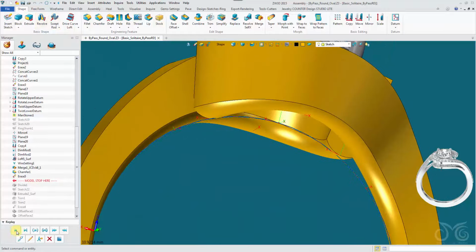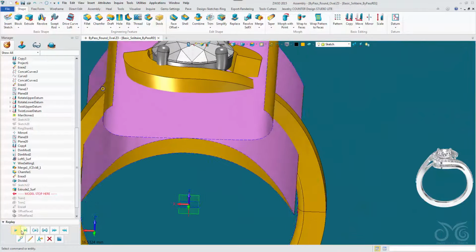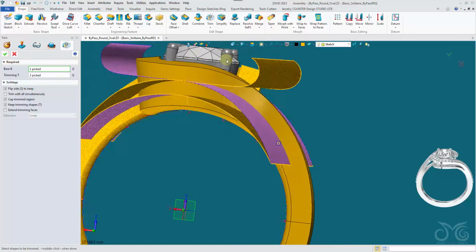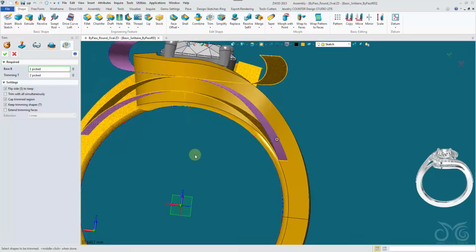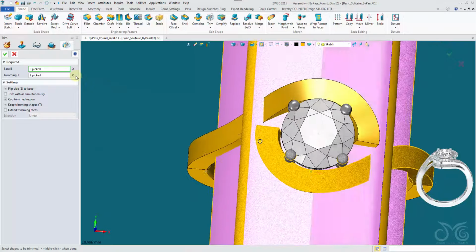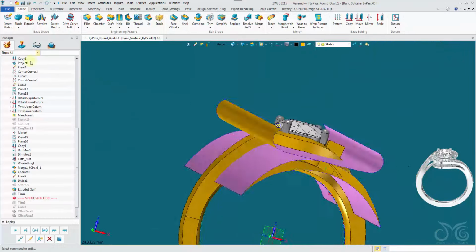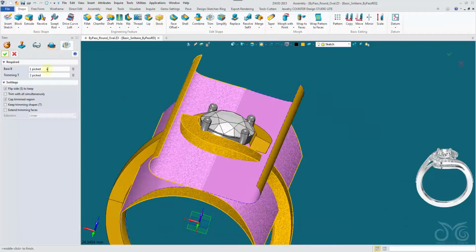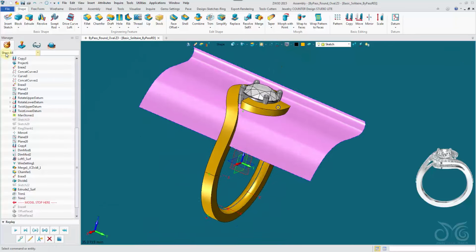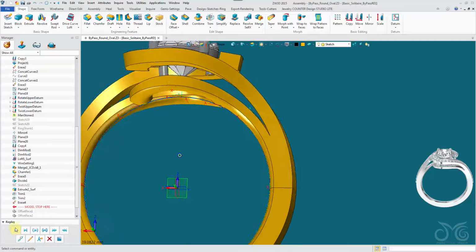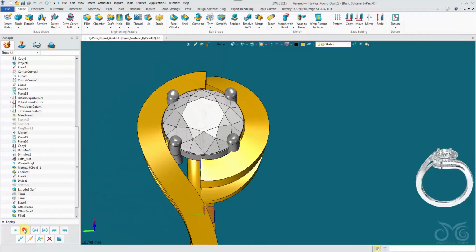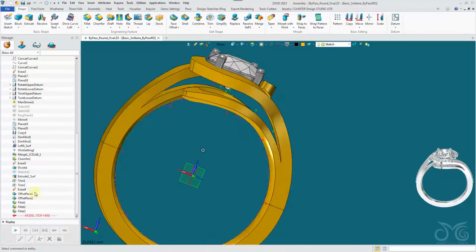Okay, now we can replay our trimming commands. We have to extrude the surface, but before we play the trim, we will edit it, and we need to include the wire settings, the prongs, in the trim. Okay, so we're trimming this side, so we want this side of the prongs. Confirm. Next one, trim, include the other side. Play the erase, and there we have our trimmed prongs. Replay the rest of history with our fillets.